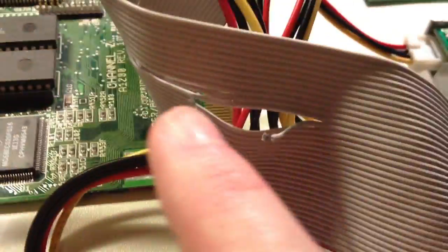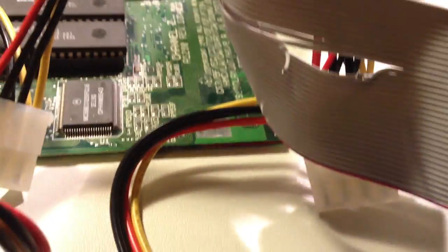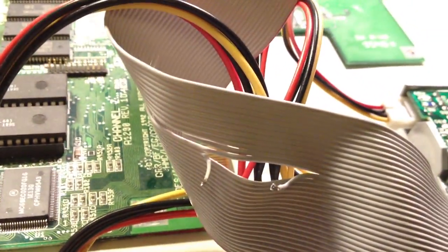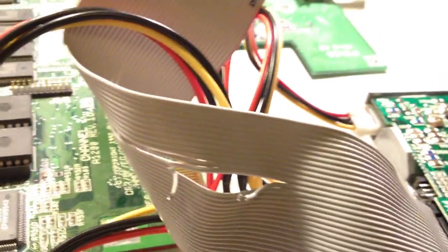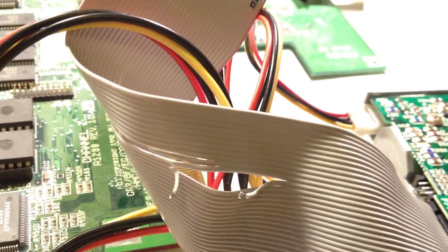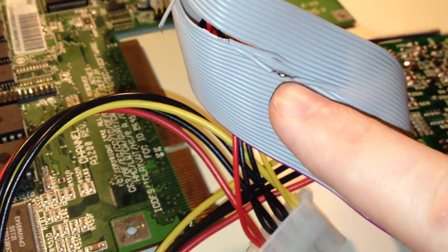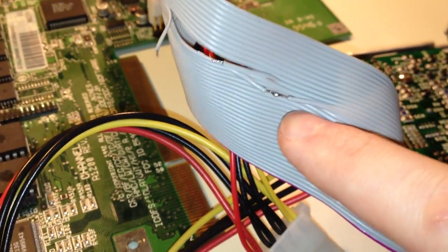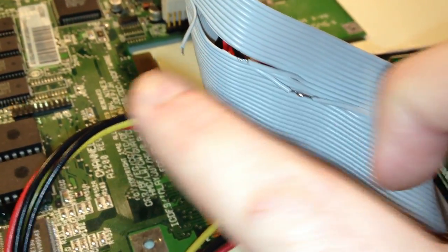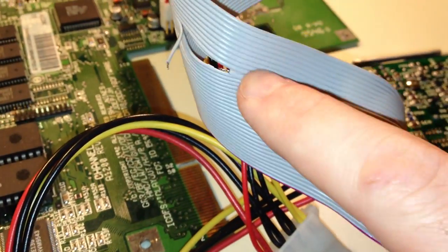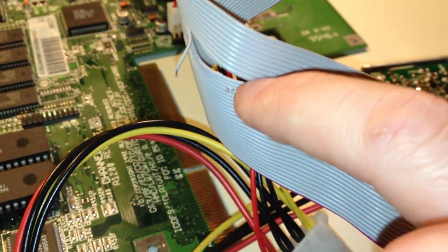So yeah, I am going to try to restore this connection and then cut the connection for the gate signal instead. And I'm going to try to format the disk again and see what happens. I have now restored the connection for the incoming serial data, and I have instead cut the connection for the gate signal. So let's try to format the disk again and see what happens.